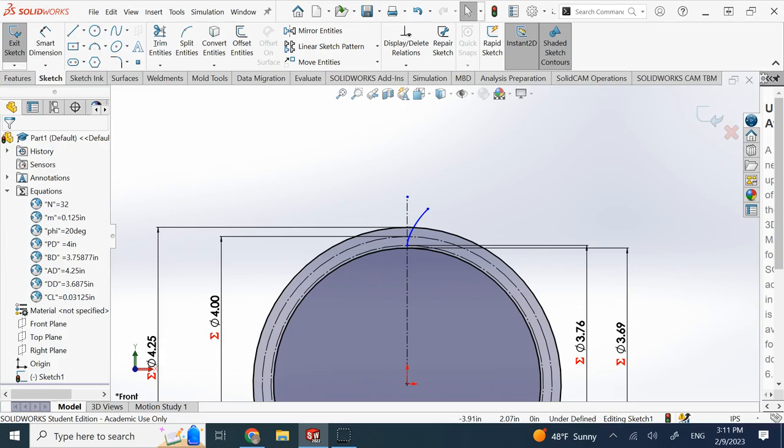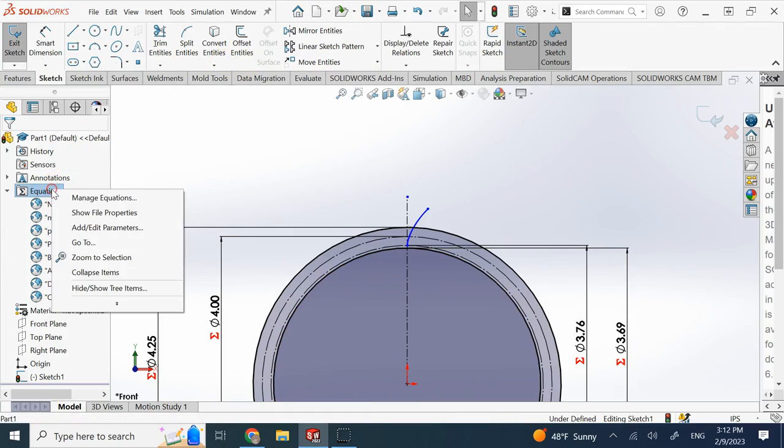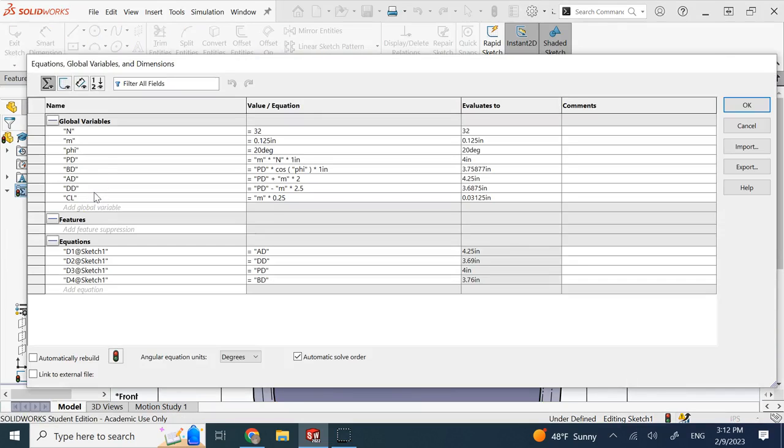And again, if you look at the equations that I provided in that CATIA lecture, this angle is going to be tangent of the pressure angle minus the pressure angle plus pi over 2n, where n is the number of teeth. So let's see if I can type in a formula for that. I can first calculate it here.